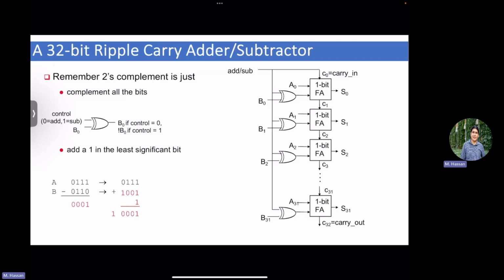But our ALU, in fact, would have only 32-bit as an output. Why? So where is this result going to be written at the end? In the register file. After I add, I'm going to take the result and write it to the register file. The width of the register is 32-bit. I cannot have more than 32-bit as an output from the ALU going to the register file. The 33rd bit that I'm going to use is the overflow. This is the meaning of an overflow. Basically, it means your output is larger than what you can accommodate in your width.